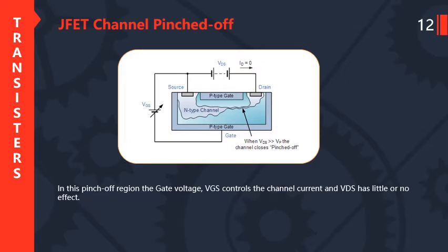JFET channel pinched off. In this pinched off region, the gate voltage VGS controls the channel current and VDS has little or no effect.